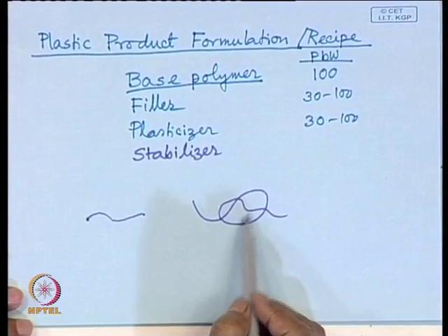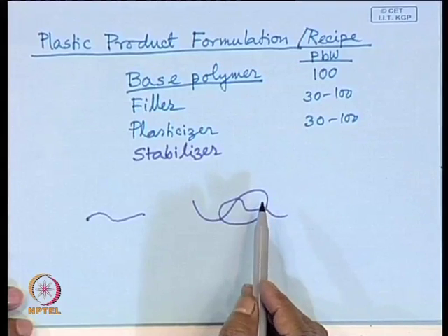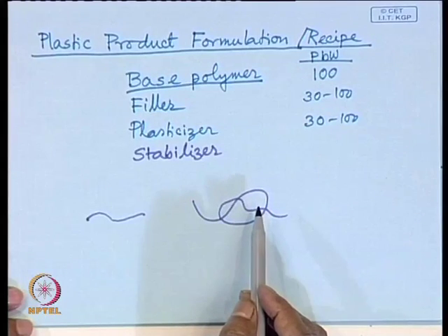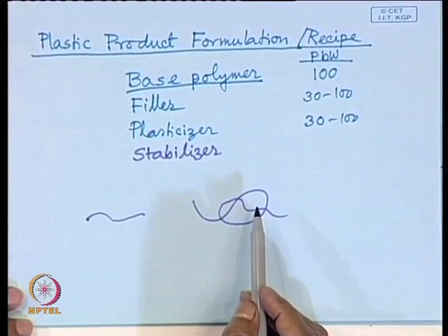So, here if you add, say, 100 parts of filler to 100 parts of polymer, you can incorporate it, and you will be surprised to know that in some rubber products, to 100 parts of rubber, more than 1000 parts of fillers are incorporated. Say floor mats, floor rubber mats, these are made by simple incorporation of river bed silt, clay filler. Their clay is used as filler.